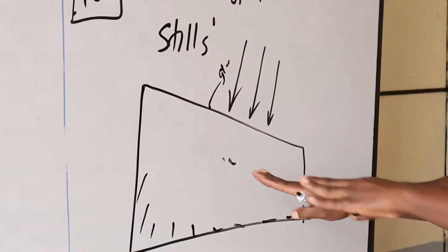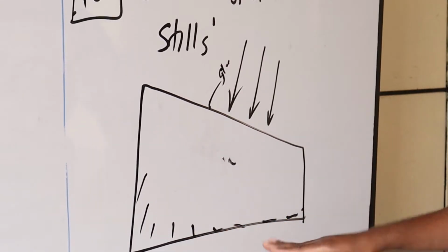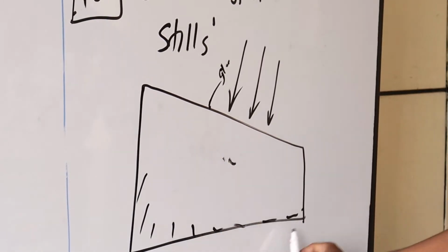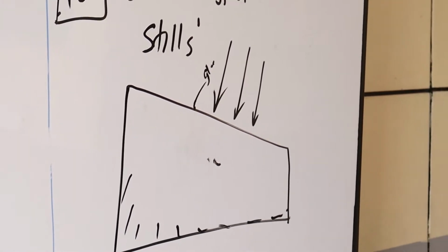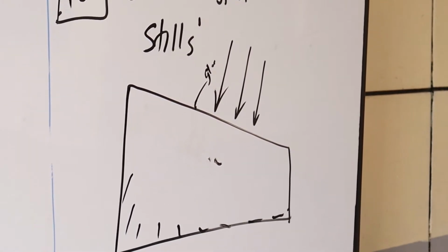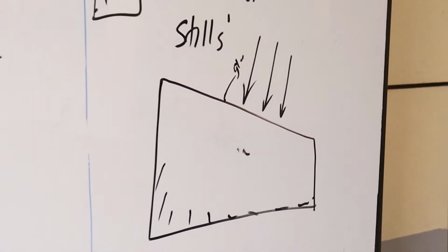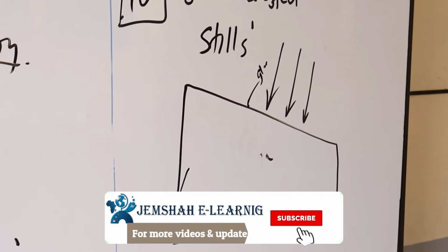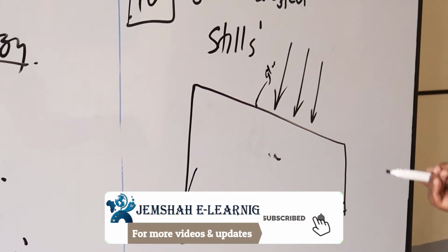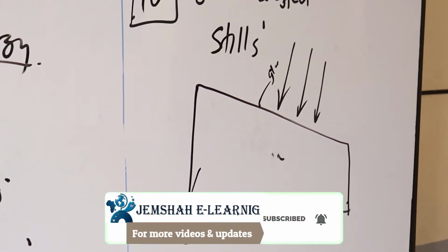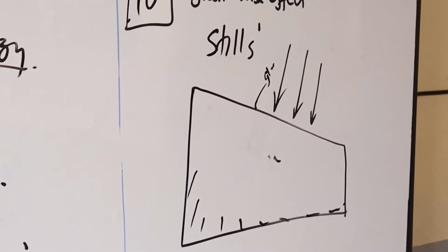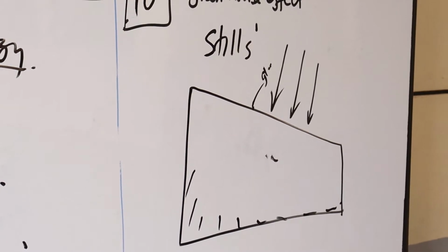Then, because it is painted black, it will absorb the heat, and after absorbing the heat, this place will have a higher temperature. So the heat, in terms of what we refer to as the infrared, will be trapped inside the solar collector, and that trapped infrared heat will cause the temperature to rise inside the box.